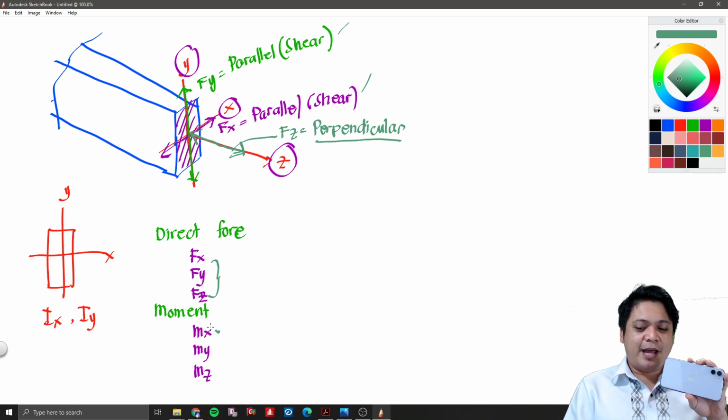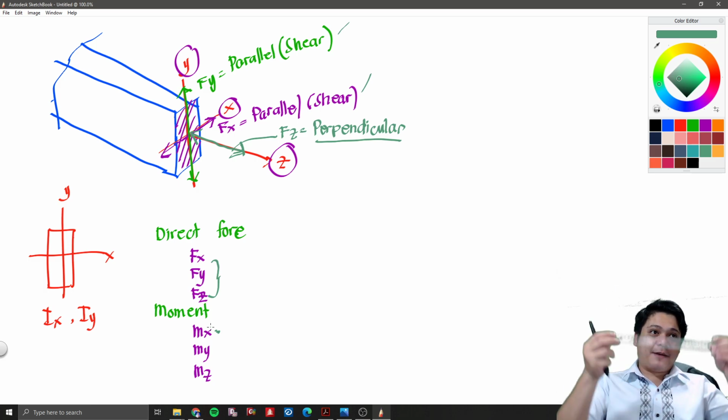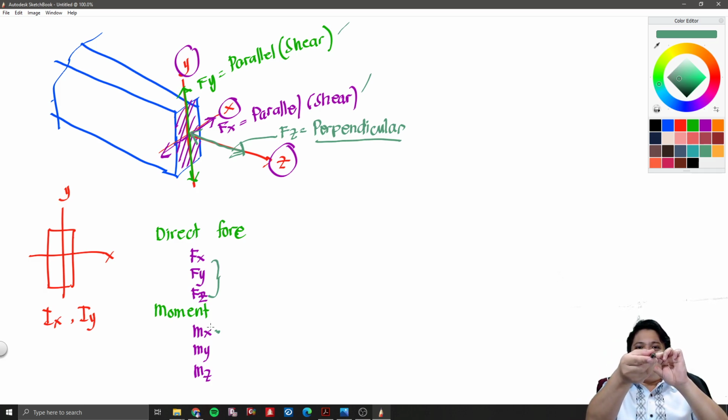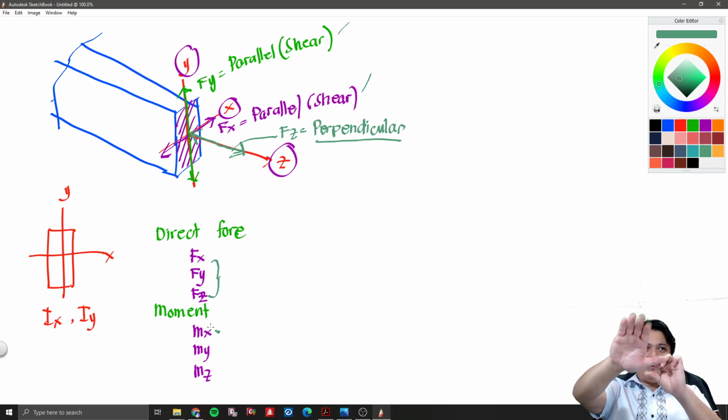Okay? How about the MX? Okay. Now, our MX, okay, it's easier with a ruler, no? Let me repeat. So, this is the X. This is the Y. And then, you have here the Z axis. Okay? So, we will always follow what you call the right thumb rule. Okay? So, if I'm telling you MX, you point the right thumb parallel to the axis. X, this is my X, parallel. And then you open your right hand, and then you bend it like that.